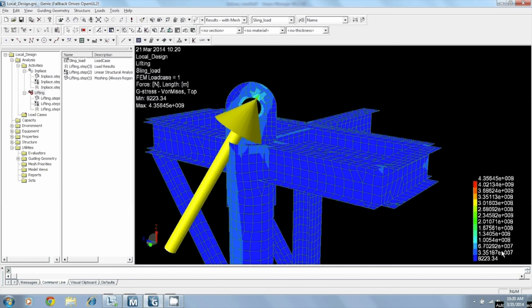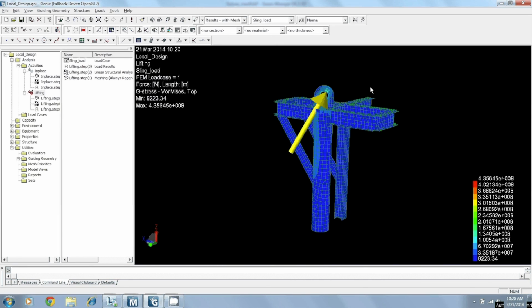And the stresses are listed here. The contour of the stresses is listed on the right side here. So this is the kind of control that you have using Sesam, and it's really one of the big advantages of using Sesam that you can go from structural code checks into a finite element mesh. This is using the same software. I did not have to resort to any second software to perform any particular purpose.